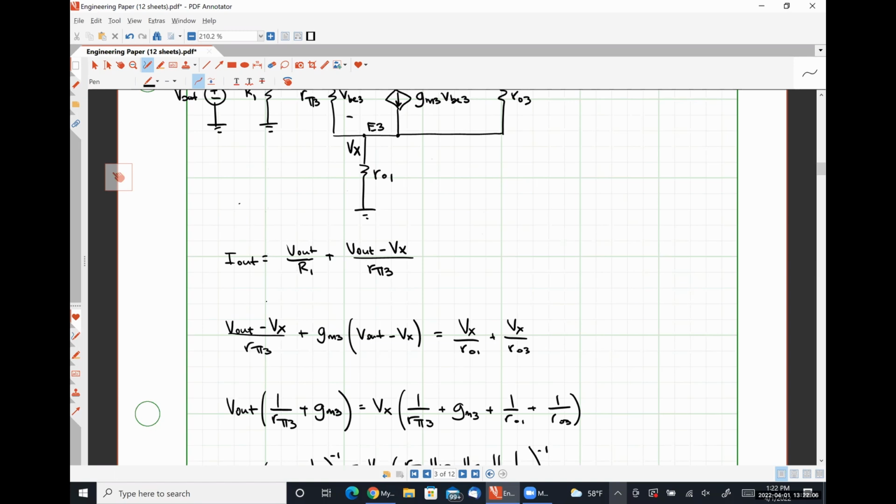Whereas if you can look at it and say, okay, looking down, I see this thing which has this output resistance. Looking up, I see this thing which has that output resistance. Those two things must be in parallel. That just eliminated a ton of work. Then you only have to concern yourself with a short circuit transconductance calculation and you have the gain.